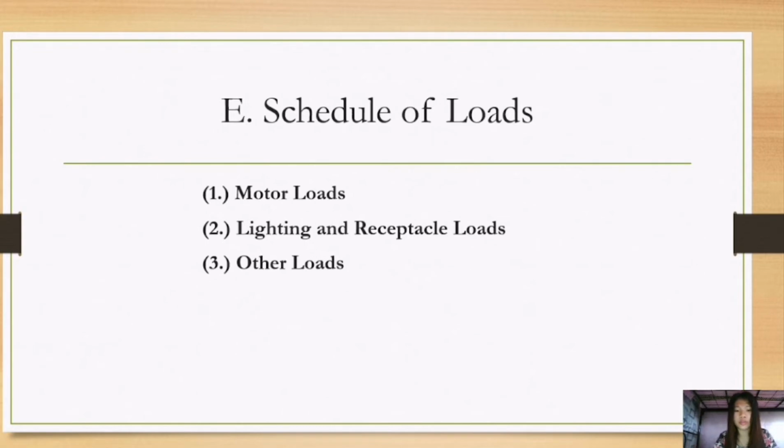For other loads, we have designation number or plan, description of load, classification of service duty if required, rating of kilovolt, ampere, or kilowatt, phase load indicating full load line current, voltage rating, type and size of wiring, and lastly, protective device rating.